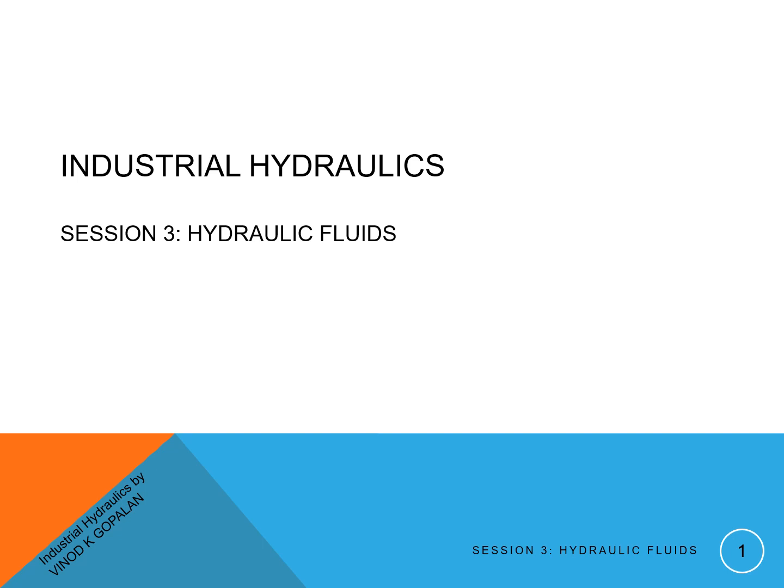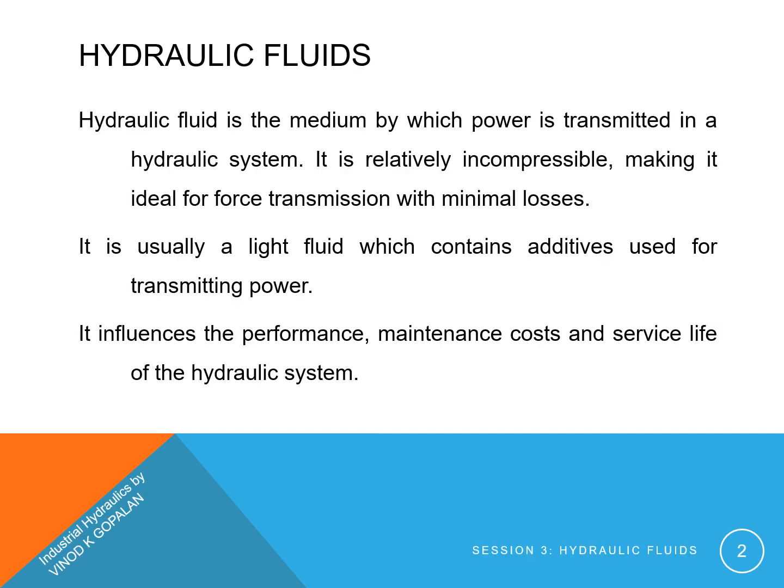Our today's topic is hydraulic fluids. Hydraulic fluid is the medium by which power is transmitted in a hydraulic system. It is relatively incompressible, making it ideal for force transmission with minimal losses. It is usually a light fluid which contains additives used for transmitting power. It influences the performance, maintenance costs, and service life of the hydraulic system.